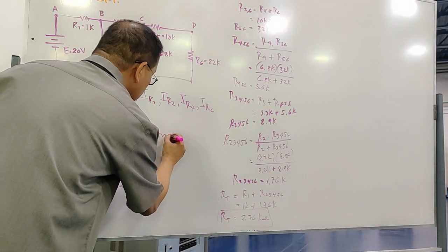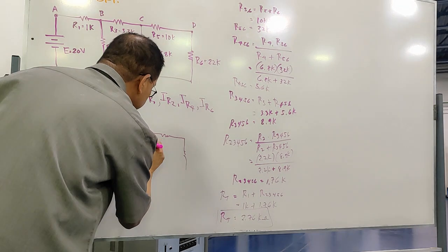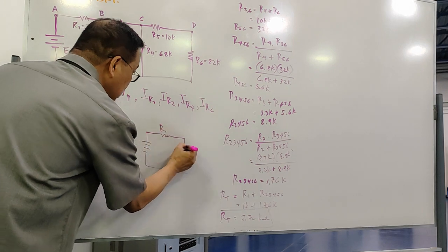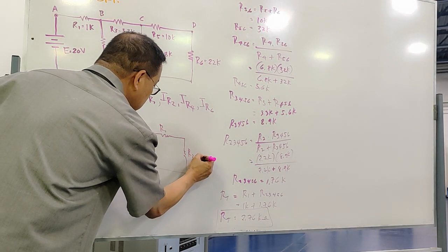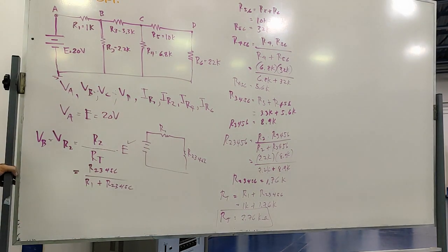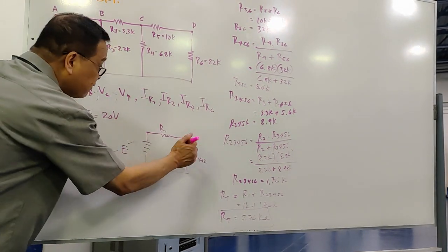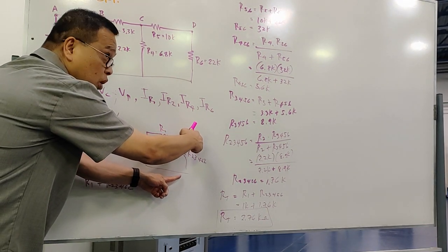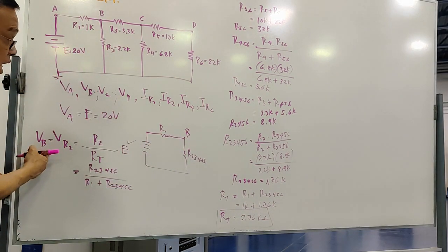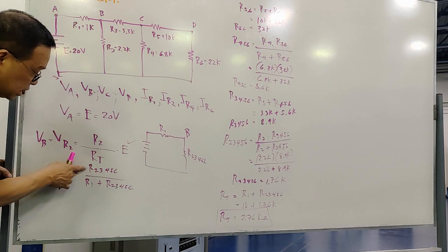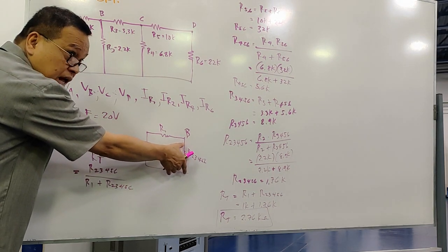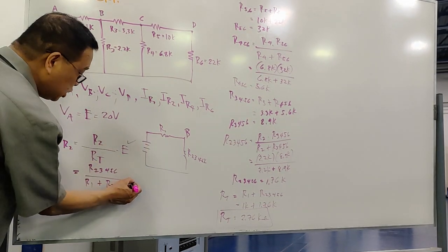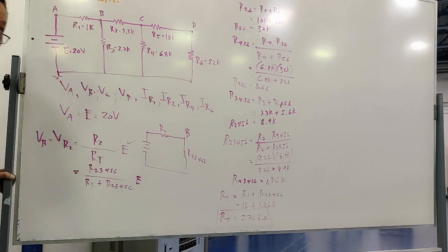Look, because the last circuit that we have is this one. So this is R1. This is R2, 3, 4, 5, 6. Is that correct? So when you apply the divider rule, since we are after point B here, we are after VR2. So the voltage here is the value of the resistance over the total in series, multiplied by the source, which is here.